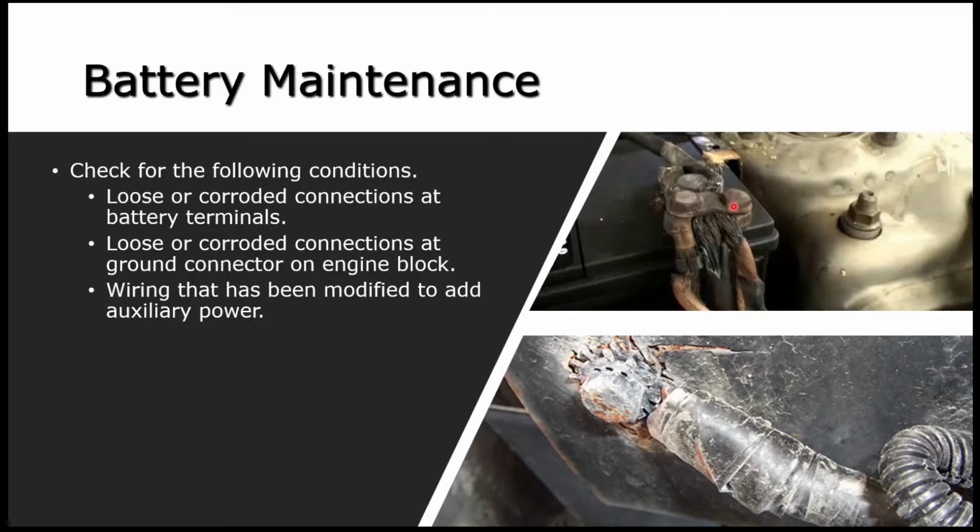They're for emergencies. In the event that you need one in an emergency, it'll get you by, but it then needs to be replaced with a proper terminal in the proper format at a later date. This is not a proper terminal, proper format. This is an emergency terminal that was put on and left there, and now you can start to see the corrosion that takes place. This is a side post ground where it mounts to it, and this here is corroded and rotted and fallen apart.